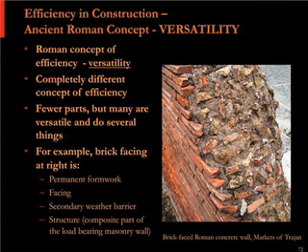So for example, this really common Roman concrete construction that you see at the right, the brick there is doing a whole bunch of things. So the brick facing is the permanent formwork for the building. That's actually installed while the wall is going up.